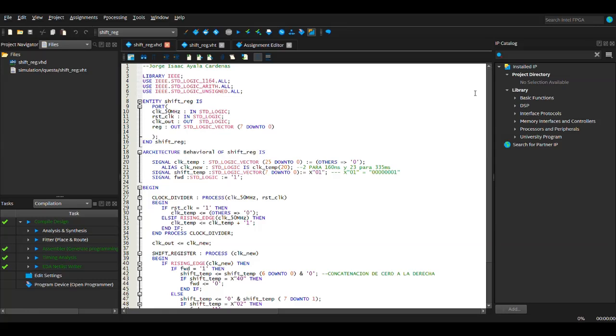The clock divider reduces the 15 MHz input clock frequency to a much slower one, around 48 Hz, so that the LED movement is visible to the human eye. To do this, I use a 26-bit counter, and bit number 20 was selected as the divided clock input.